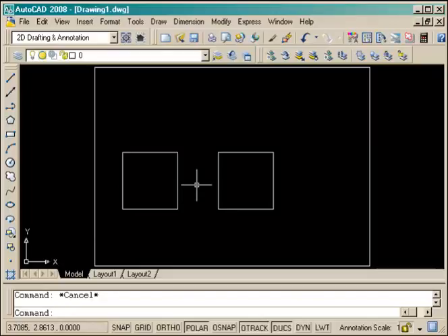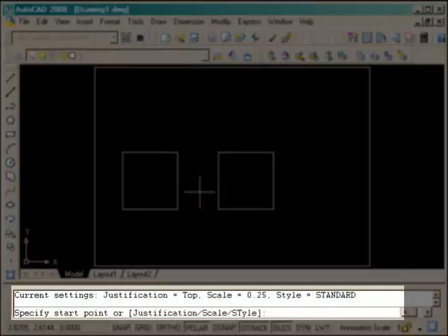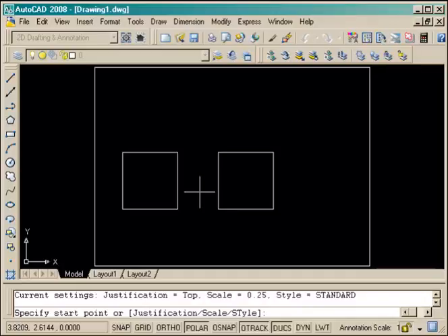The next one is the third rectangle, and for this we're going to use the Multiline command, which isn't something I use a lot, mainly because I don't have full command over the lines. You'll be setting the width of the lines, known as the scale. So you start with ML for Multiline, then pick S for scale, which is currently at 0.25, and we want it at 0.15. So enter that and press enter, and now we can start it.